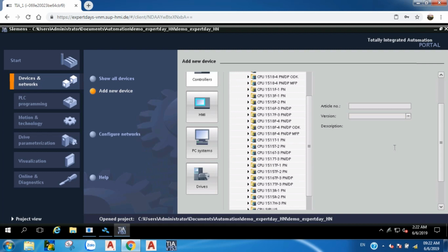When we come to WinCC, we start with a new setting for the panels regarding persistent message buffer. What does that mean? Persistent message buffer means that when you restart the system and you don't have alarms in an archive, and you still want to see the messages in your alarm control, the messages are still available when you enable the persistent message buffer in your runtime settings.